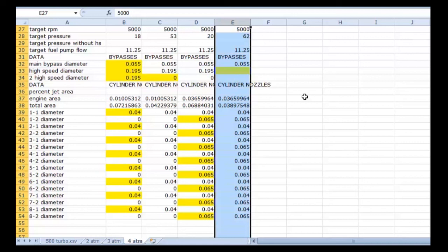This one involves simply 2 solenoids shutting a bypass off on one and another bypass off on another, and another solenoid turning on a set of nozzles on the other. So for 3 parts, 3 additional pathways, electrical pathways, you can accomplish the jetting profiles from idle all the way up to very high boost levels. It's conceivable that you could add more steps and go to even higher boost levels and compute all of the nozzles and the jetting ahead of time, again in virtual reality, and profile an entire engine combination.